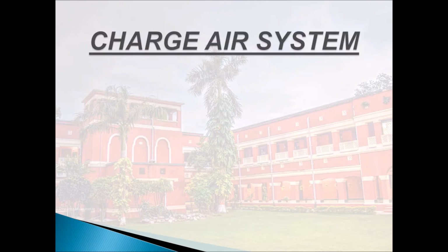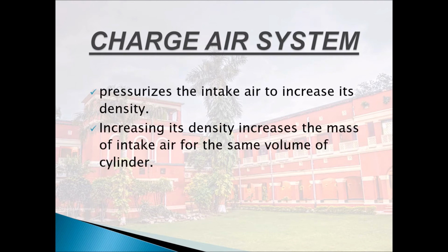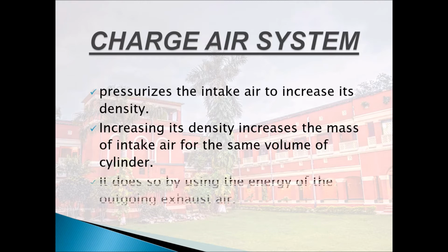So basically the charger system pressurizes the intake air, increasing its density, which results in an increase in the mass of the intake air for the same volume of the cylinder, and it does so by using the energy of the exhaust air which is coming out through the chimney.